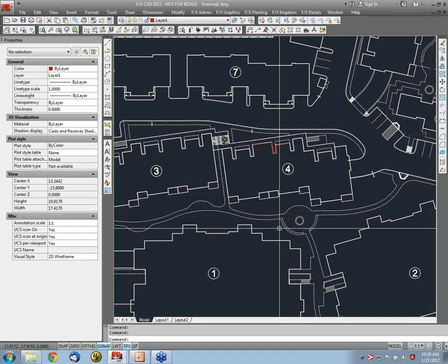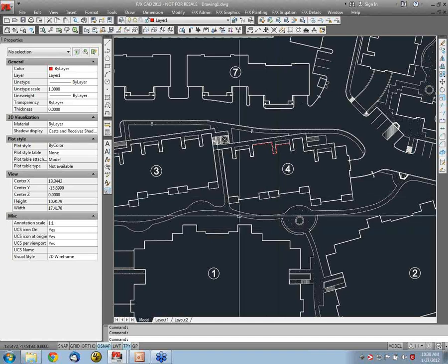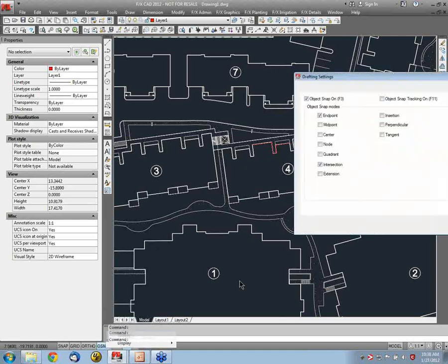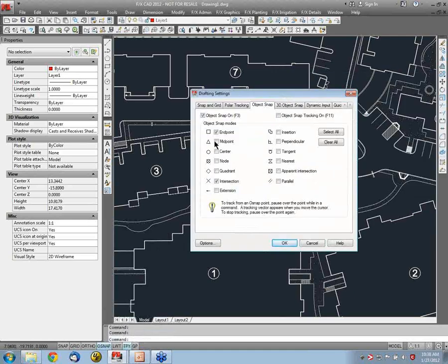While you still have this PDF up, we got another question. You did snap to the end of the line. What about the other snap functions, midpoint, that sort of thing? Yes, I'd imagine we could snap to all kinds of things: midpoint, center, and certainly nearest, parallel, and paired intersection.